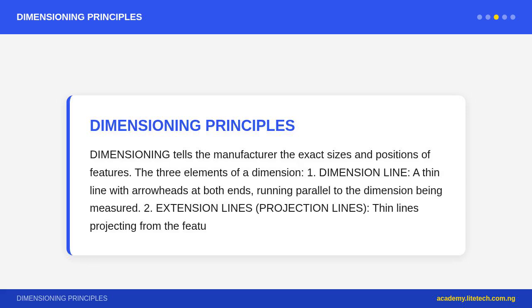Dimensioning special features. Diameter, prefix the value with the circle with diagonal line symbol. Example, 25 means diameter 25 mm. For circles in circular view, the dimension line passes through the center with arrowheads at the circumference. Radius, prefix with R. Example, R15 means radius 15 mm, dimension line starts at center, arrow at circumference. If center is off the drawing, the line is broken with a kink. Square section, prefix with the square symbol. Example, 20 means 20 mm square cross section.